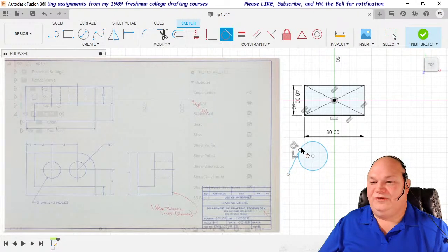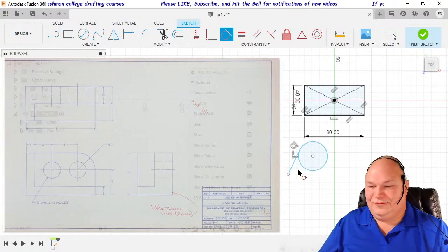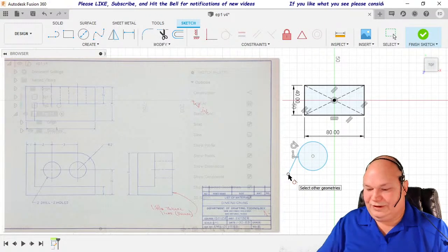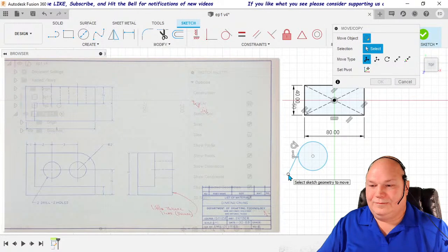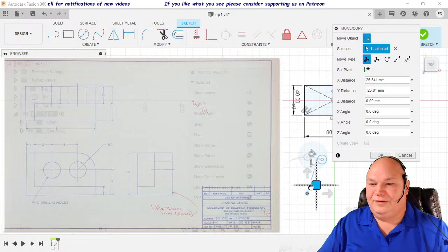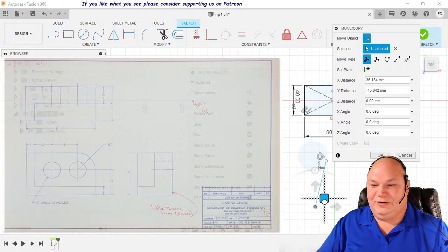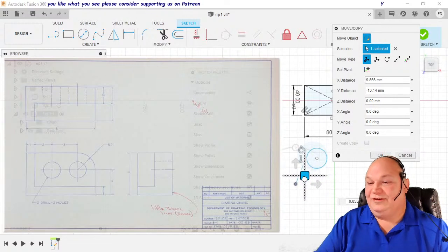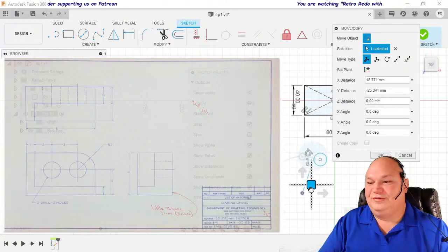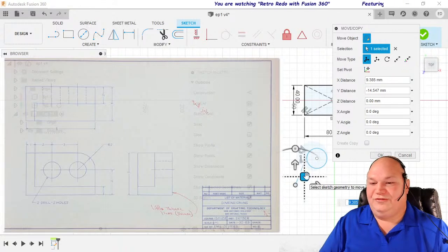Now your line is perfectly lined up with the edge of the circle, which is convenient, of course, for various things. But if I then take this end of the line and decide to move that line around, it's going to keep that line tangent to the circle, and apparently in the same direction. And since I didn't say how big my circle was, it's saying, okay, I can change the size of the circle. I can change where you move, because you didn't give any other definitions.